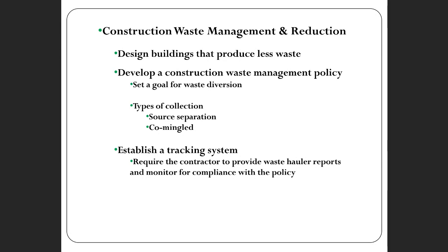Develop a construction waste management policy. That would be you as the designer specifying that and expecting the contractor to follow your practice. Establish a tracking system. You're going to require the contractor to provide hauler reports about where that waste goes and how it's handled.